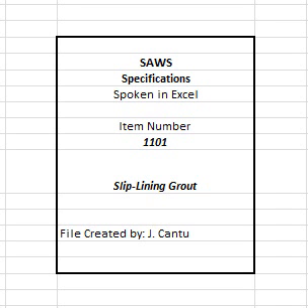1101.3 Materials. 1. Manufacture/application: the applicator of the grout mix shall be certified by the grout mix manufacturer and approved by the engineer. The certified applicator shall be regularly engaged in the placement of grout, including completion of pipeline grouting installations having at least 1,000 cubic yards in the past 3 years.